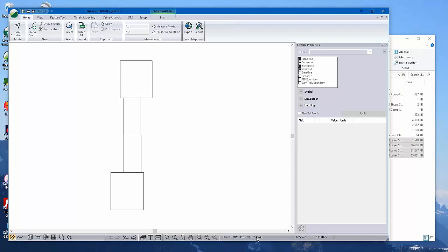With version 8, we've increased the number of points that we can handle. It's virtually unlimited. It's bound only by how much memory you have. But realistically, I'd say try to keep the number of points in your surface under 10 million. I mean, it's really about speed, computational speed, and things like that. With 10 million points, you're probably going to be working quite quickly. So that's just a rule of thumb. Some projects you might want to go up higher. Some you'll make them less.